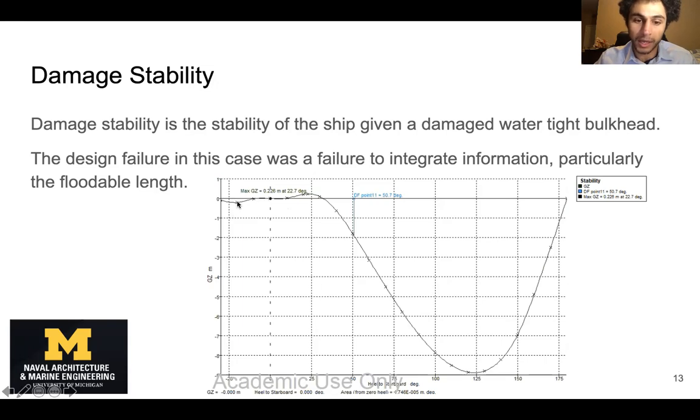You can also see that there's actually negative righting arm in the beginning. So that means that if the ship is heeling at these smaller angles, it's going to have force against the correcting. Positive stability right here indicates that when the ship is tilting like this, the positive righting arm moment says that it's going to go back up like that. And when you have negative stability, it's actually going to go the opposite way, and the ship is going to sink itself.